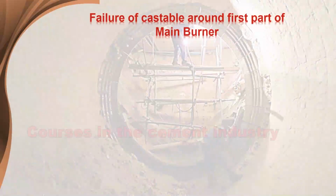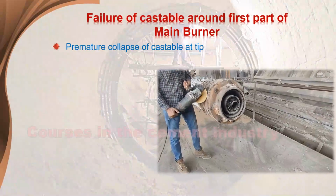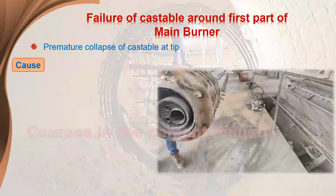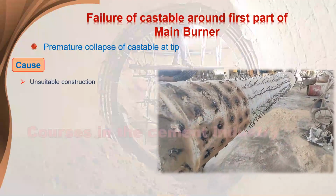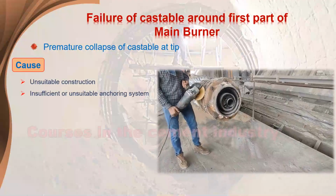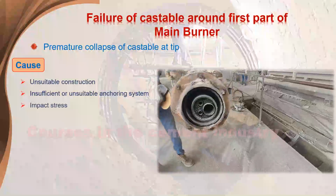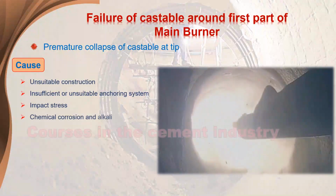Failure of castable around first part of main burner. Premature collapse of castable at tip. Cause: 1. Unsuitable construction. 2. Insufficient or unsuitable anchoring system. 3. Impact stress. 4. Chemical corrosion and alkali. 5. Coating fragments falling off.